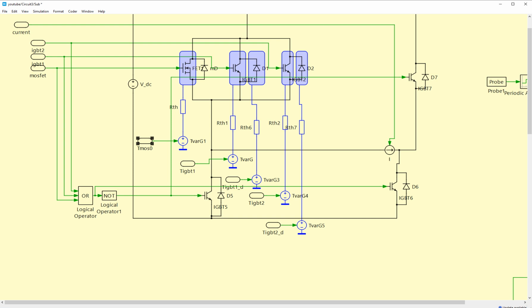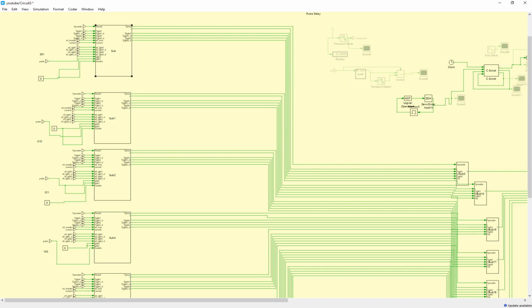Very simple. The reason for doing this is that the initial temperature right at the beginning of each switching period is given from outside, from the optimization. The optimization picks the best state for each switching period, and then according to that, you have to keep track of the junction temperature of the corresponding best state.